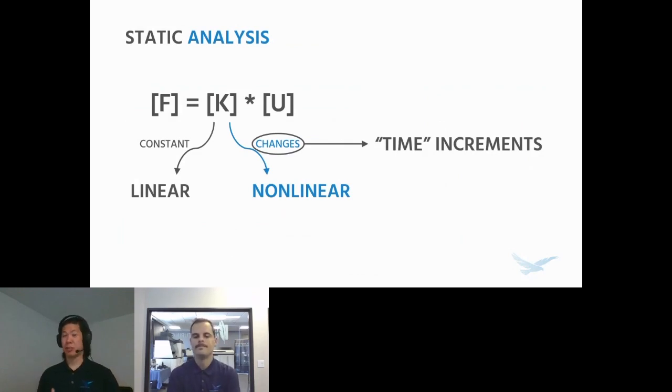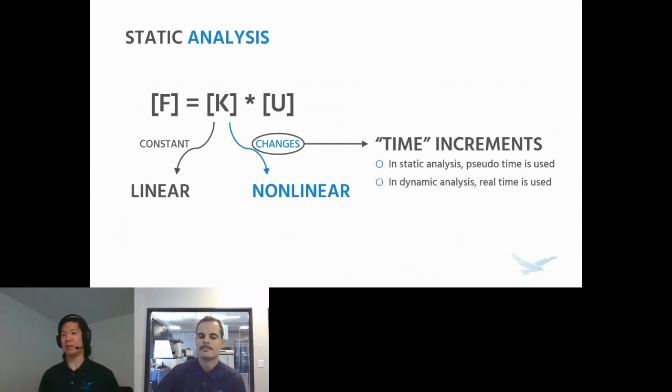That's because if we're talking about static analysis, there shouldn't really be any time. Instead, these time increments are then just a way for us to increment the load or other conditions that we might have applied to our model. Sometimes we'll refer to that as pseudo time. Of course, if we are talking about a dynamic analysis, then these time increments are real time increments.